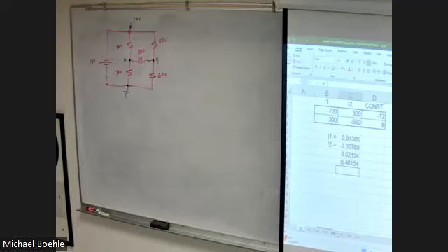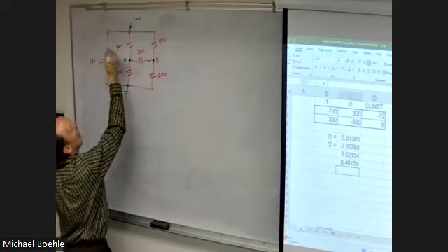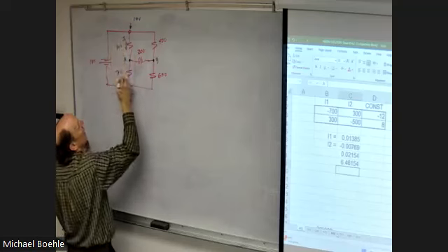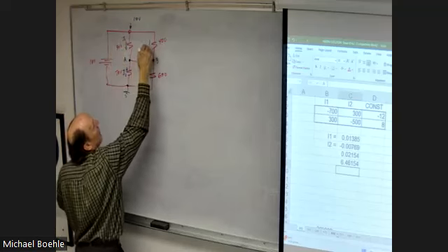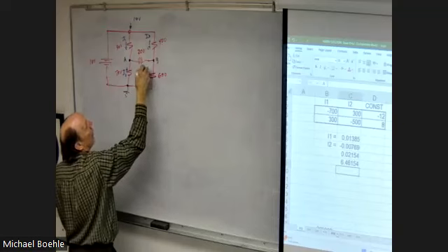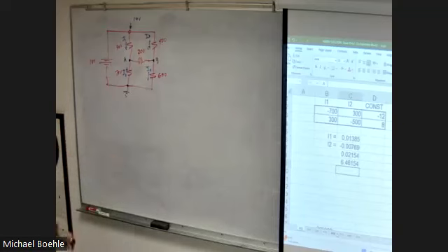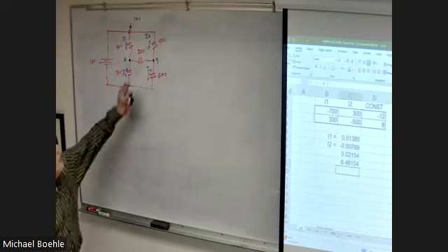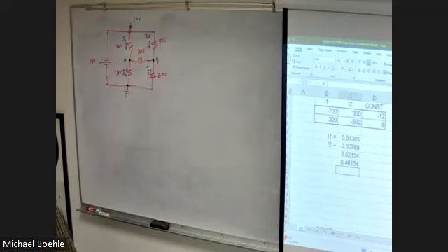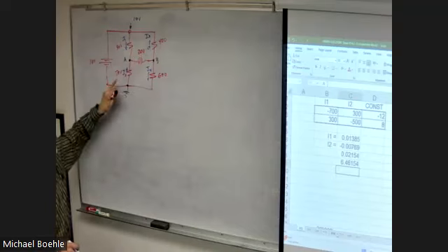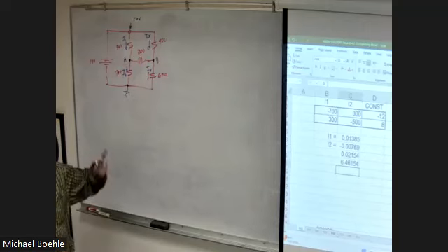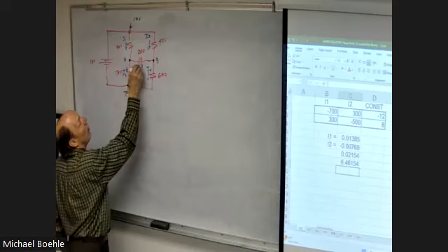All right. So based on that, I'll make my assumption here that this will be current 1. We'll call that current 2. I'm guessing the directions here, hopefully accurately, current 4. Now, what about here? Which direction is that current going to go? Left to right or right to left? Any guesses, based on the values that I have here? I'll give you a hint. If this resistor is not there, I can actually solve this circuit, right? With respect to ground, the voltage here would be 7, the voltage here would be 6, and when I put the resistor in, that means the current will flow that way.